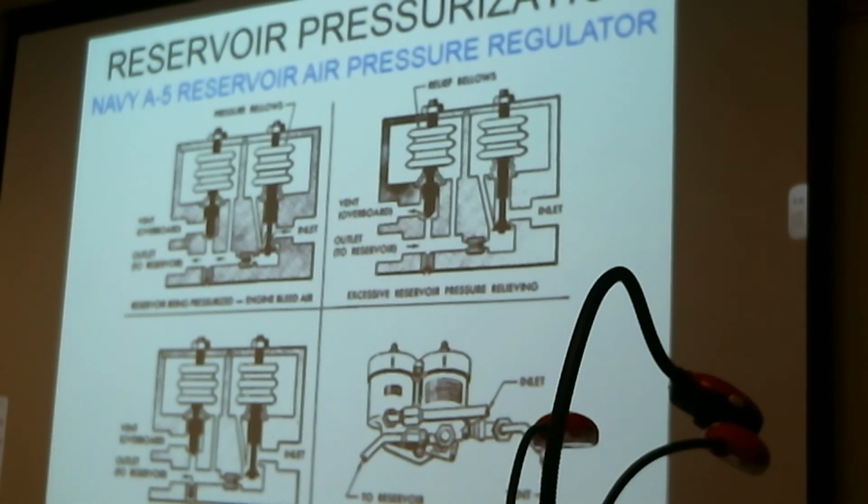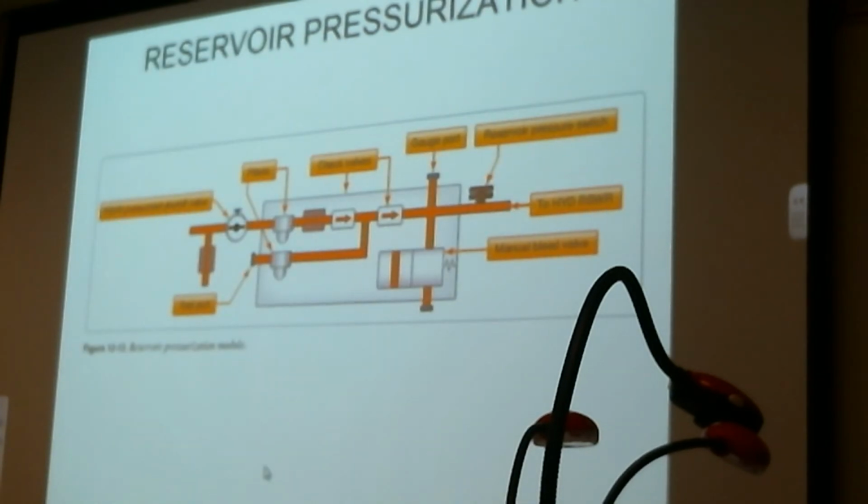And also we have to provide for vacuum relief inside of the reservoir. So sometimes they've got a little check valve that's mounted on the reservoir. This prevents the reservoir walls from imploding. So it allows air pressure to enter into the reservoir to prevent negative pressure from collapse. Okay. Circuit from your book that shows your reservoir pressurization.